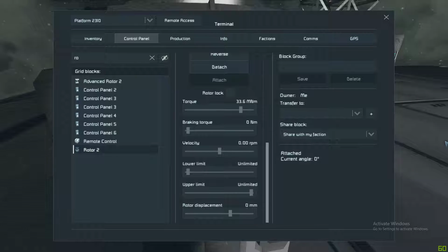One thing about torque is very important to understand. If you have too much braking torque and you've got a very heavy object on the end of the rotor, the object will decelerate very quickly, but the inertia will keep going, and that could likely snap the rotor head off. So you need to be very careful when you adjust these, adjusting them for weight, speed, etc.